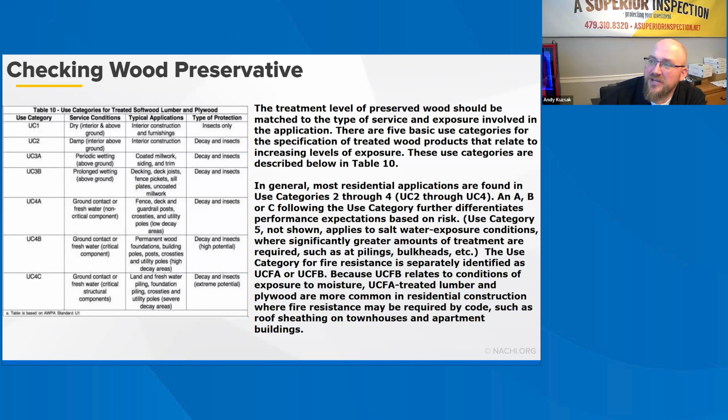In recent years, changes have occurred in the availability of certain wood preservative treatment chemicals for the use in residential projects. Therefore, it is important to understand how these changes affect treatment requirements for various types of wood and applications. In particular, the use of CCA, chromiated copper arsenate, has been discontinued as a wood treatment except in certain commercial and agricultural applications. However, there are exceptions.